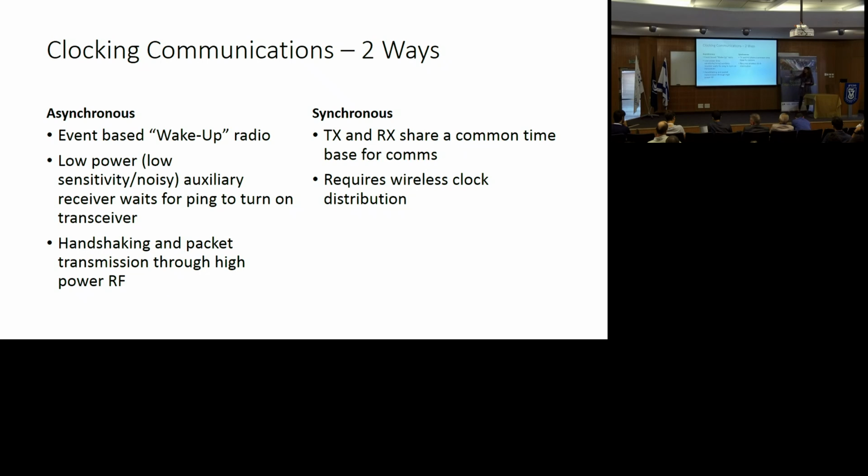But there are other versions of this asynchronous that are not wake up, where you have a regular wake up, where I'm going to wake up according to my local clock, and you're just hoping that your local clock overlaps with whatever it's sending to you. It might take a lot of cycles for that to happen, but that's an alternative version of this, and that does exist. So with the synchronous version, one potential advantage, though I'm not sure how huge, is that you don't have two radios. You have one radio.